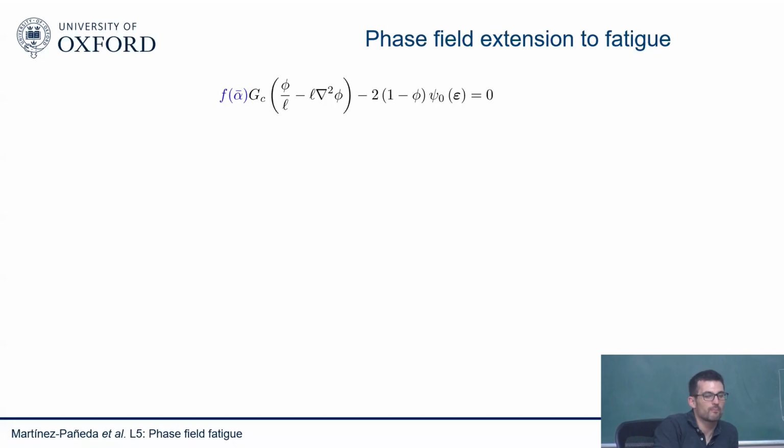Yeah. It's a little bit inconsistent if you just take phase field fracture for brittle materials, right? So even there, you're still saying once a crack is propagating, your fracture toughness of the material is actually degrading. So you could actually have the 1 minus phi. But you don't degrade your fracture toughness, right? Your fracture toughness is a constant. You degrade your balance of linear momentum, right? And then here you have a phase field degradation. So phase field fatigue continues to degrade this.